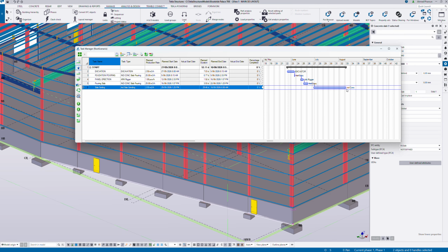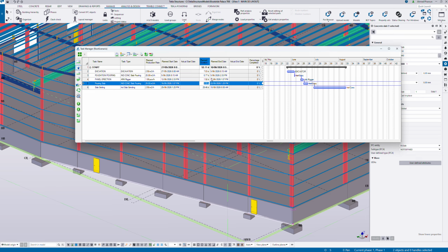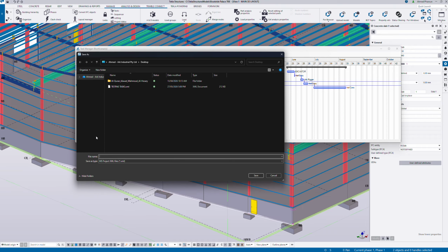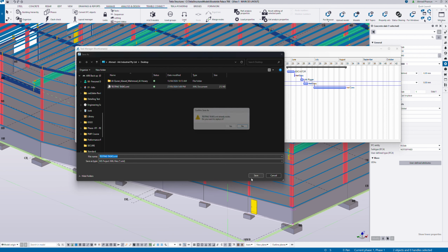So we can have here the duration for each task in the project added automatically from the model according to the data that comes out from the model, and we can add the lag between the tasks and get a chart. How we can make use of this with our project team to help them in their planning: once we have the structure of the tasks here, we can just export this file as an XML file directly to Microsoft Project.